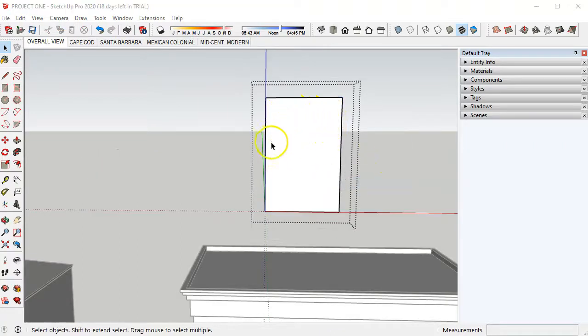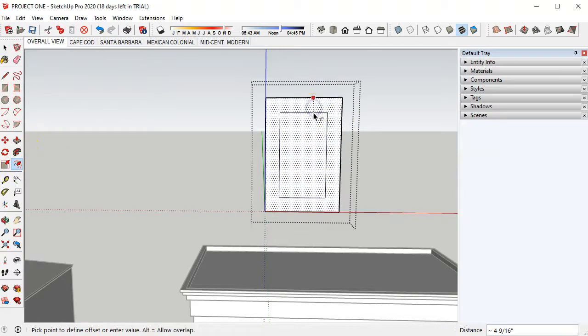For the main parts of the door, the stiles and the rails here, we want to again go to the offset and pick on the perimeter. For this one, you can just look in the lower right hand corner and see what the distance is. That's 2 inches. For our scale of homes, since these are really small or tiny, maybe 2 inches is good, maybe 2.5 or so. I wouldn't go beyond 3 inches for the main offset of this first part. So let's just put 2.5 inches.